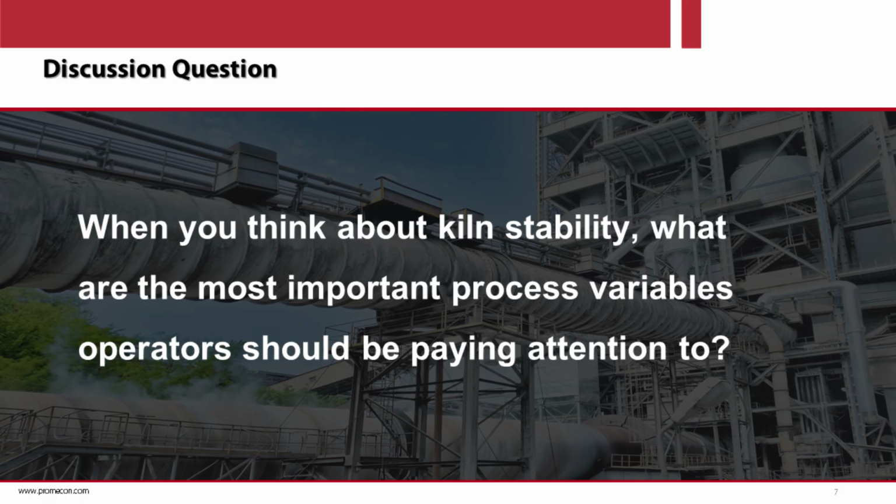Thank you, John, for that question. First of all, if I have to rank them, I will rank the flow first, and the draft or static pressure second. Why I'm making that claim is that, in the literature, you could say that a static pressure, at some place where you install those pressure transmitters, you could have a lot of turbulence, for instance, and those values could vary a lot.